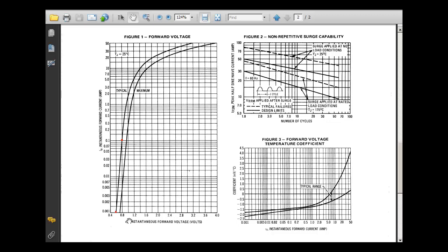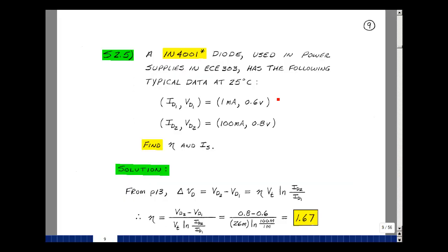across it. But you can see here it looks kind of bizarre because this is a log scale. So when we're looking at an exponential, it'll be a straight line. Eventually we'll talk about this over here, which is actually the resistance of the contacts of the wires going into the semiconductor. I grabbed two data points off of here. One at 0.8 volts, which was about 0.1 amp, which is 100 milliamps. And then the other point over here on the bottom at 0.6 volts, and the value about 1 milliamp. That's where this data is coming from.